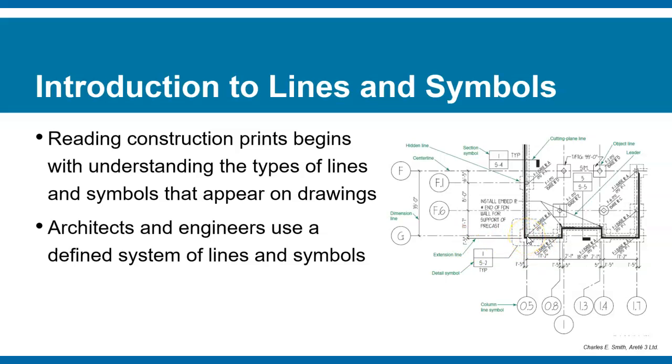Those are important to know when you're pouring the foundation and then having the wall set in relationship to that foundation, so that these dimensions mean something. You see, you have again another 1.5 feet that's referencing from the center line off of center column line symbol 0.5. So we could say this is center line 0.5 and this is center line G.